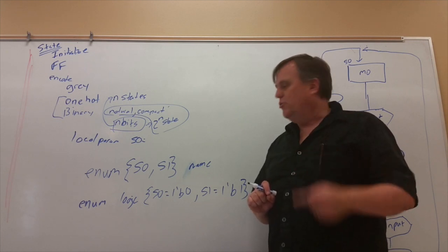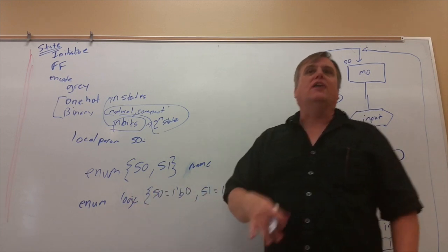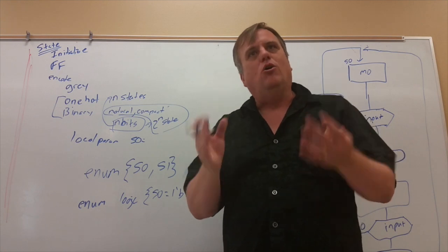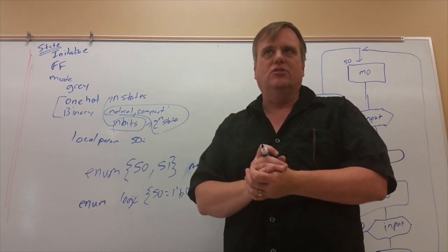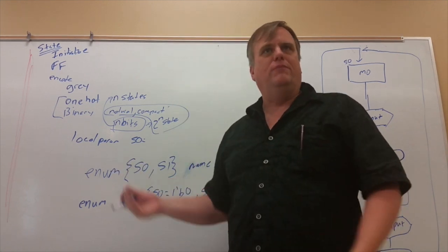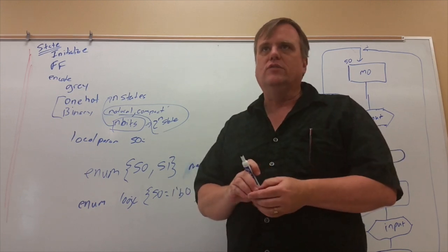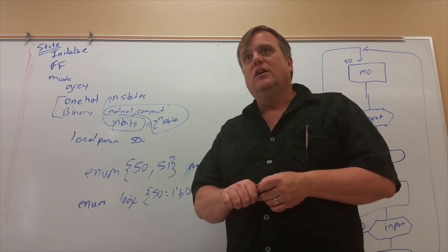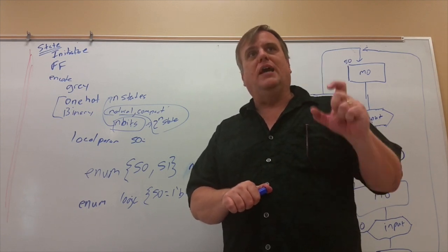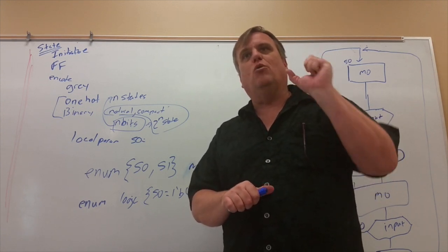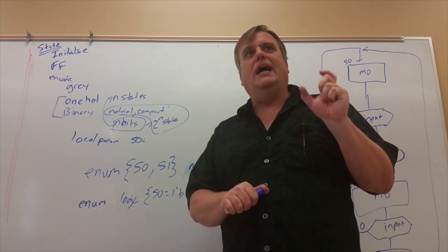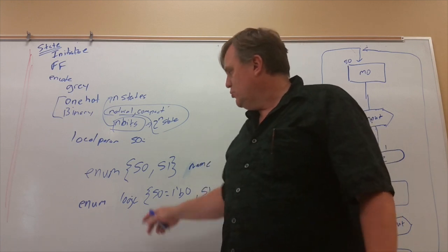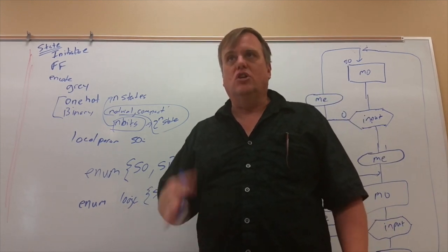So logic is not only a simpler way of not having to pick wire and reg, it also specifies a design intent, that I want all of my bits to eventually end up as 0s and 1s, because that's what's synthesizable within my system. If you want to be able to synthesize not 0 or 1, you have to do a different thing like a wire, because this will not allow you to synthesize non-0, 1.